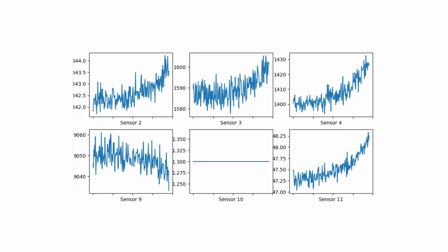And we can see the PF curve, the potential failure and the functional failure in real sensor data. So we have the CMAPS data here, which is the data of a simulated engine. And you can see different sensors. And in all sensors, except for the flat sensor, you can see that you have first a healthy period until the P point, and then you have a more rapid degradation afterwards, ending in the functional failure.